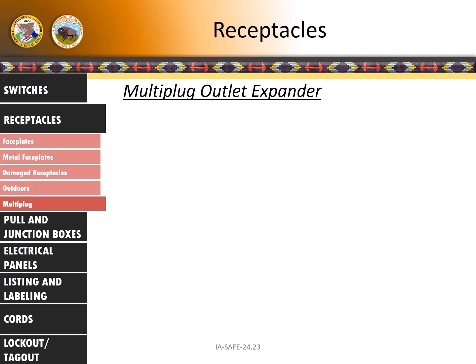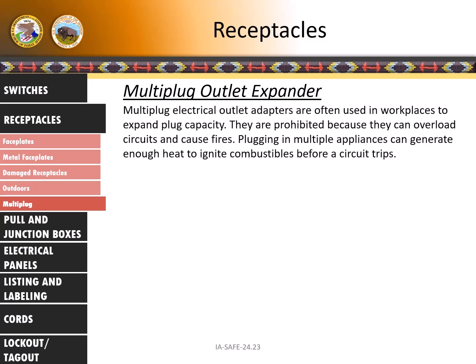Multi-plug outlet expander. Multi-plug electrical outlet adapters are often used in workplaces to expand plug capacity. They are prohibited because they can overload circuits and cause fires. Plugging in multiple appliances can generate enough heat to ignite combustibles before a circuit trips.